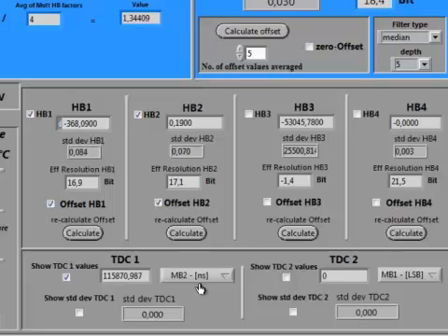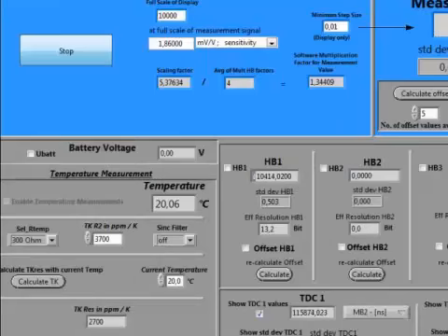The discharge time usually lies in the range of 70 to 150 microseconds. You can check if the system is working correctly by checking if the discharge time shown here is in accordance with the discharge time that you designed for. You can read the value of the supply voltage currently being measured by the PS09 from this box here. You can disable or enable the evaluation software from reading this result by clicking on this box.